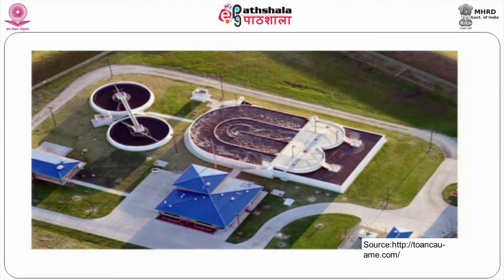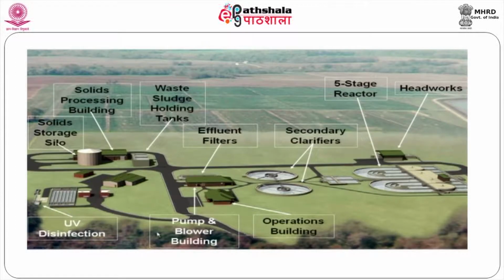This is a bioreactor normally provided for oxidation ditch. Subsequently, we have secondary settler. At the downstream side of secondary settler, we have sludge dewatering facility to remove solid from liquid phase. So, this is the aerial photograph of STP incorporating oxidation ditch as a secondary treatment facility.